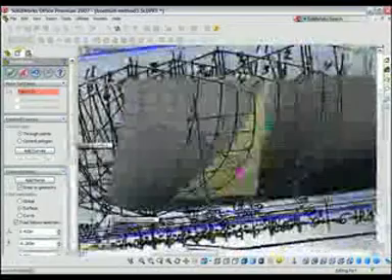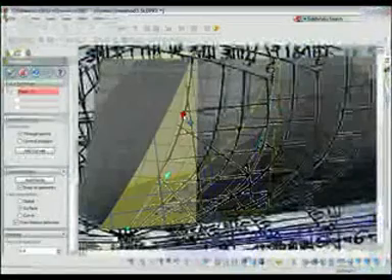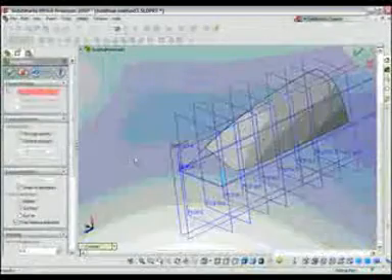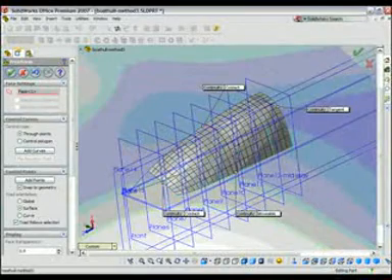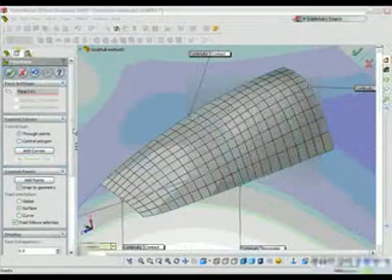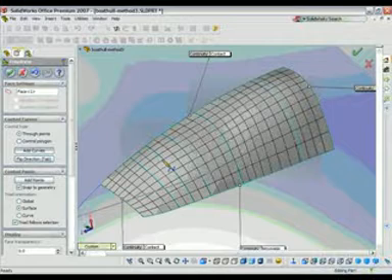And we'll finish with this last one. And this one I think I'll just drag the front top vector to match that. And now we have our surface roughed in. It's close to these sections, but if we turn on our mesh, you can see there's some deviation going from the back to the front.